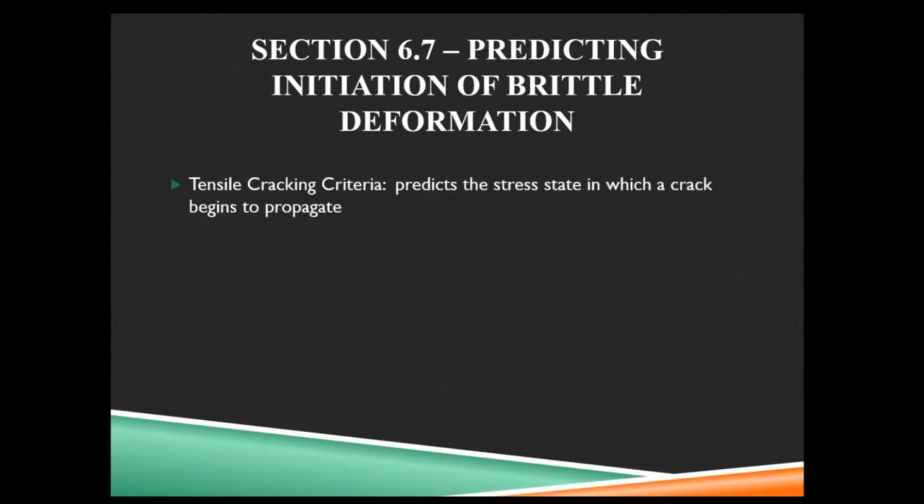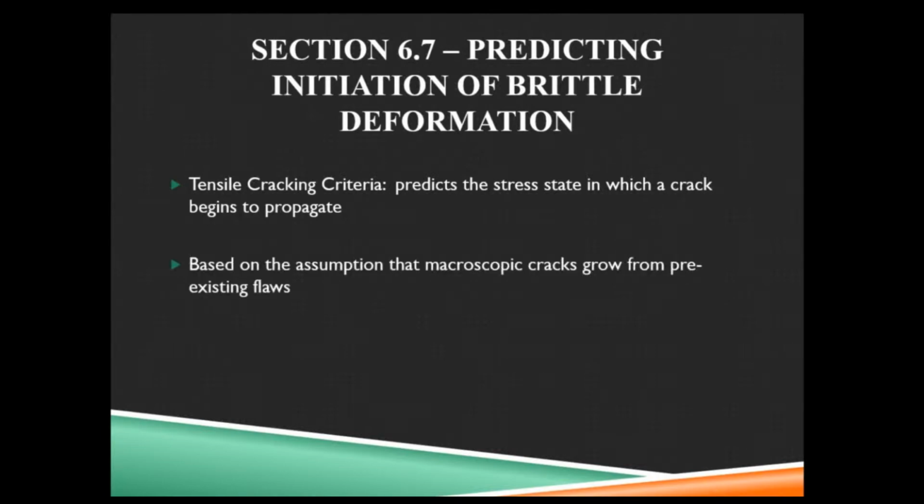Tensile cracking criteria. This is what we use to predict the stress conditions that will make the rock break, that'll make the cracks grow. Now, this is based on the assumption that macroscopic cracks, big ones, big enough to see, grow from pre-existing flaws, from those Griffith cracks.